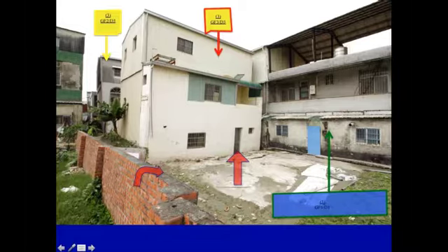In stark contrast, the long building on the right, likely of similar unit lineal weight, let's say, in terms of just scanning at their elevation, and surrounding ground failure characteristics just adjacent to them. Nonetheless, the ground failure right adjacent to the building we classified as minor, and ensuing only minor cosmetic structural damage was observed. Its foundation and structural system was highly continuous, and no exterior single-story additions were observed along the features of this particular building on the right. So you see it's got a blue interior and green perimeter color coding associated with GF1 and D1 respectively.